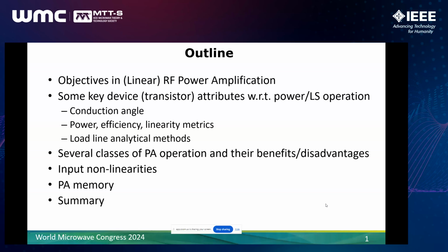And then lastly, PA memory, which is particularly important for linearization such as digital pre-distortion, but even without DPD, it leads to difficulties in that there's asymmetries in sidebands or IM products and so on. And then finally, I'll summarize the results and draw some conclusions.